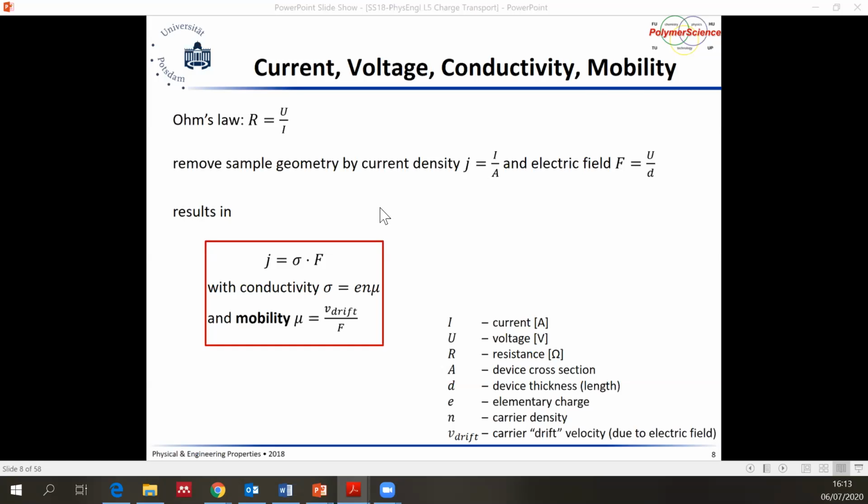So this makes it difficult to have a defined border between insulators and semiconductors, as in some cases, insulators can be treated as wide band gap semiconductors if carriers can be excited to their LUMO or conduction band, either through photoexcitation, sometimes called photodoping, but let's just call it photoexcitation, or if we introduce an ionized point to the lattice, so we do electrical doping.